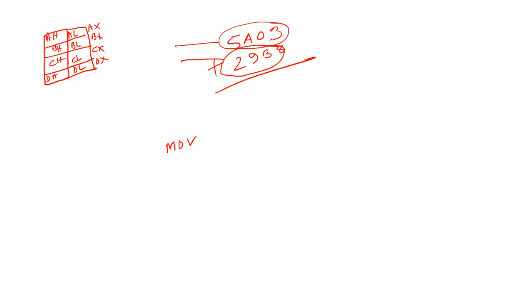This is the 16-bit. 1, 2, 3, 4. 16-bit means you must use AX. If you use an 8-bit program, then AL, AH, BL, BH is no problem. This is the 16-bit, so this is the 8-bit and this is the 8-bit. So full is needed. Then the code is AX. Clear? Yes, sir. So our code is MOV AX, comma, 5A03. Okay, this data is transferred to our AX register.